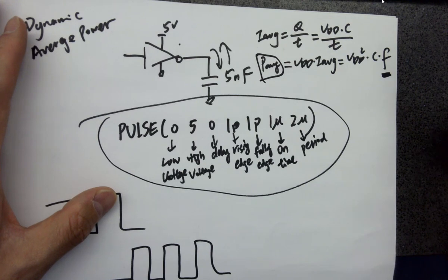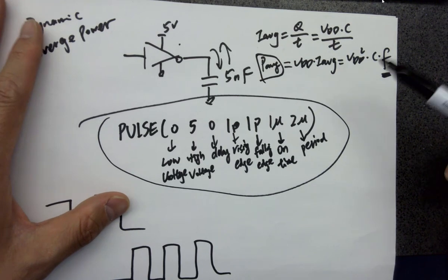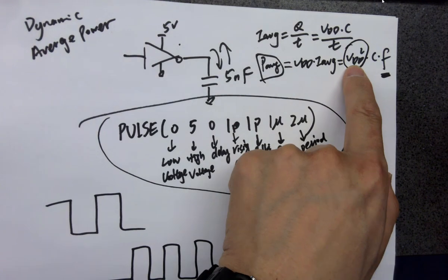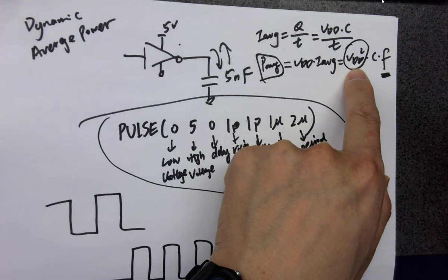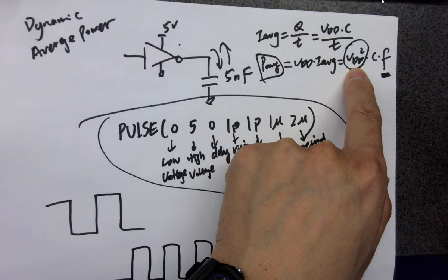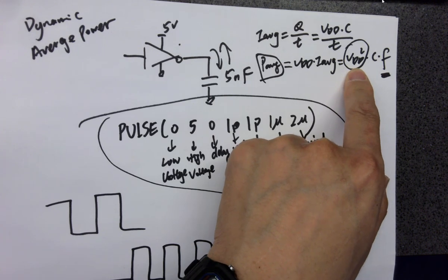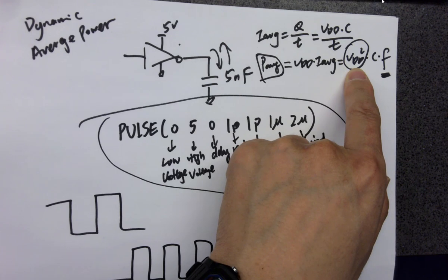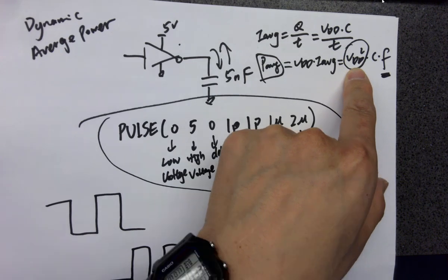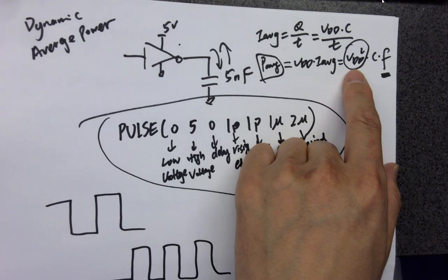For digital circuits, we want to reduce the VDD, the power supply. You have probably noticed the 180 nanometer technology we have been using. The transistor's name is PMOS 3, and that's the one using a relatively higher voltage.